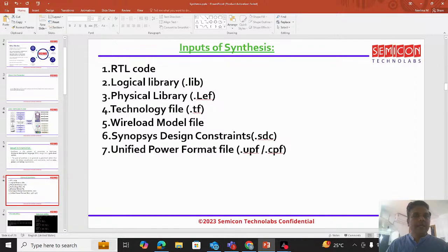In that case, to save the power, we need to break the entire design into multiple portions, and each portion can be independently turned on and turned off. This can be done by keeping each of these portions in power domains, which we physically call voltage areas, right? These individual voltage areas can be controlled to turn on and turn off, thereby saving leakage power and dynamic power, right? And dynamic power, as we know, is internally of two types: one is internal power and another is switching power, right?